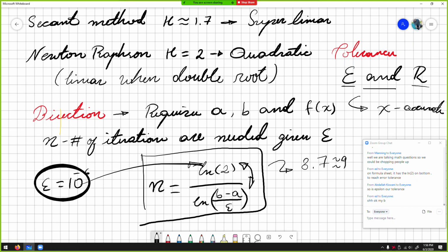Like if the real value for a mass is 2 kilograms or 2 grams, your solution will start at the initial guess, which is maybe 5, and then go 2.9, 2.5, 2.2, 2.1, and then start oscillating around it. If the real solution is 2, it will go 1.95, 1.955, 1.99, until it gets to 2. So it will get extremely close to the solution, and it only knows when to stop depending on the tolerances that you set up.